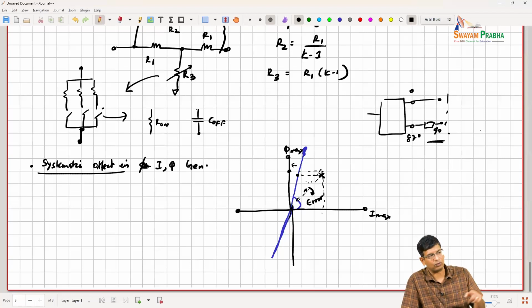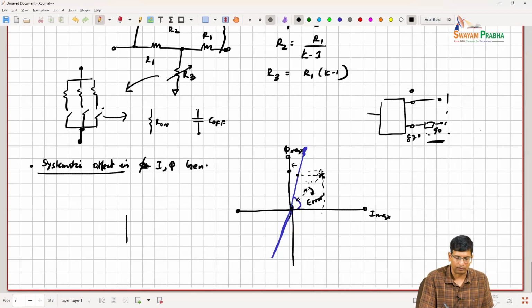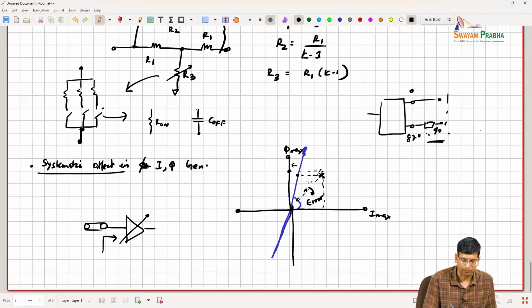But typically you can compensate for those kinds of small errors by routing or creating meanders in the design to compensate for it, right? This is a deep implementation issue, but what really causes problems is if the input of the amplifier, its Z, is changing with gain, and then we have added some compensation networks over here, and the Z over here is changing with gain.